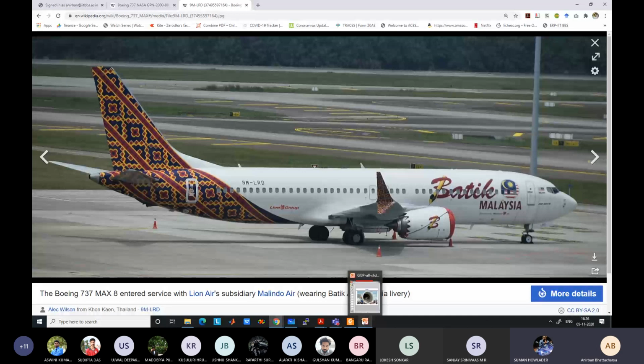When you are lifting, the entire lift is generated by the wing, right? So as if you are pulling the aircraft by the wing. If you think about a toy aircraft which you are holding by the wing, and the front side is very heavy and the back side is very light, what will happen to the toy aircraft? It will try to dip forward, go down in the forward direction. So by putting the engine forward, the load balance has shifted, meaning it has become more unstable. More weight has come towards the forward direction, forward of the wing. The weight should be equally balanced between the front and the back direction.